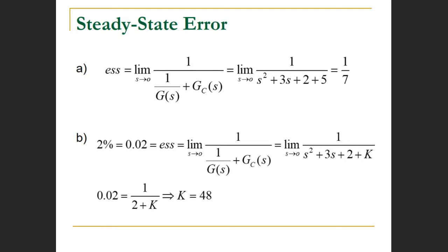Reduce significantly. But the reason why I went over to show you the plot again is that when you increase k, even though it has a positive effect, meaning that it reduces steady state error, it also causes another problem, which is the significant overshoot. So if you were to say, just by looking at the outcome here, okay, let's keep increasing k until this thing goes down to near zero, no, it doesn't work like that, because while you're doing that, something that is not supposed to happen is happening, which is the effect on the overshoot. Just bringing your attention to that.